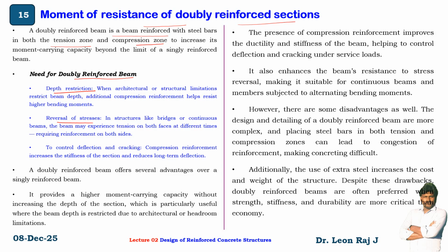Where is the reversal of stresses? What is the reversal of stresses? In earthquake forces, the force will act on both sides actually. So if this is the frame, the stress will act in this direction, and also in this direction, and also in this direction. So this is called stress reversal in both directions, cyclic loading. These are all the best examples for the cases of stress reversal.